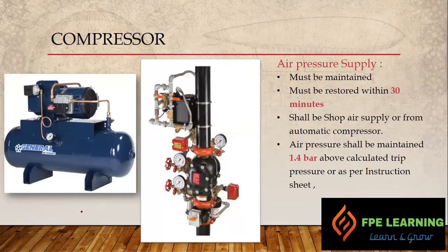Okay, so how are we going to supply air to the system, right? We can supply air from the compressor unit, or there is also a riser mounted compressor, like here we have, right? This is a riser mounted compressor. So it's based on the design requirement. If you are installing in a plant where we have instrument air easily available, then at that moment you might go with this solution, right? Not with this one, because it's very complex and requires lots of maintenance. It's costly compared to some other solutions. But again, it depends on the design and the location or requirement, right?